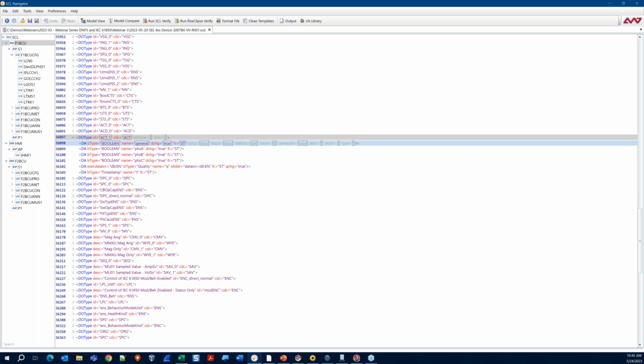And the point that I really want to drive home here is that these are the leaves at the end of the tree. This is kind of where it ends. And this is what maybe most directly corresponds to an individual DNP3 point, whereas the data object is just a container which holds multiple of these, in this case 1, 2, 3, 4. The data attribute is a single point in my DNP map to relate the two.